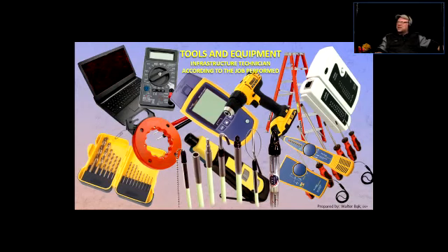And also, aside from a DMM, which is a digital multimeter, I would say it's a really good idea to also get an analog one, and that doesn't have to be expensive. You can just go and get a cheap one, because sometimes when you're measuring voltage, it fluctuates. It stays in maybe one space and just fluctuates a little bit. A digital multimeter is not going to give you an accurate reading, because it's going to try to count up and down, and you're just going to see a bunch of numbers flashing. When you have a needle, you're going to see the movement.